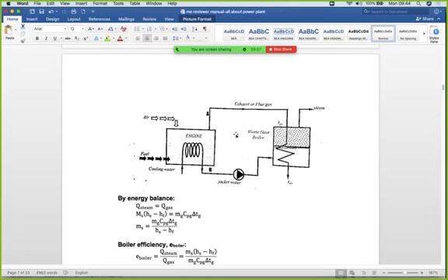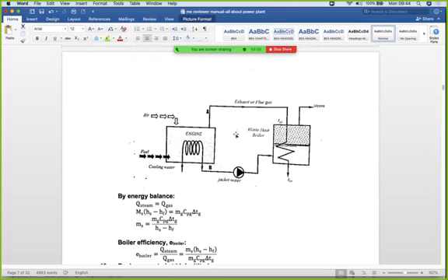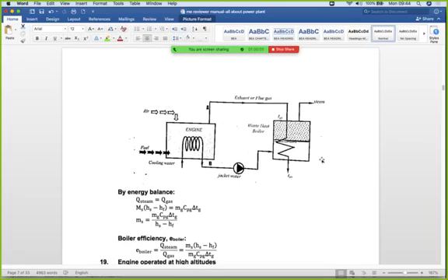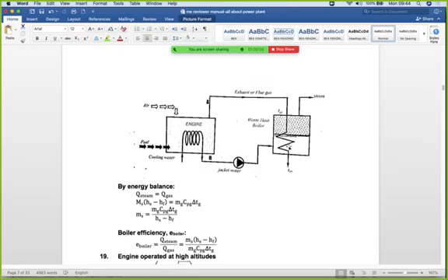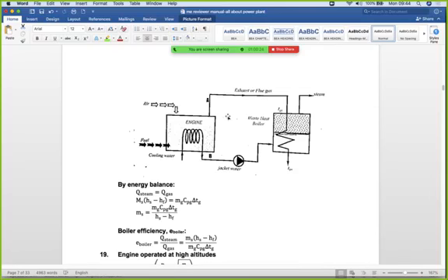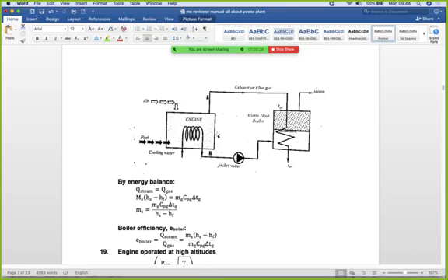So there's an increase of efficiency because this boiler is using a form of energy which is not produced by adding new fuel but by reutilizing the source of fuel: the unwanted gas, the exhaust gas from this engine here.